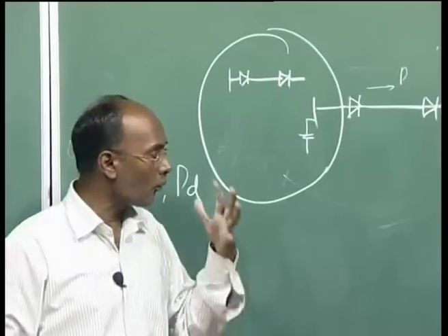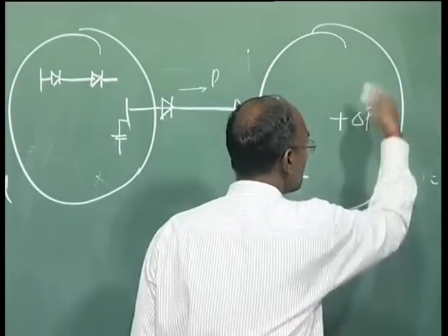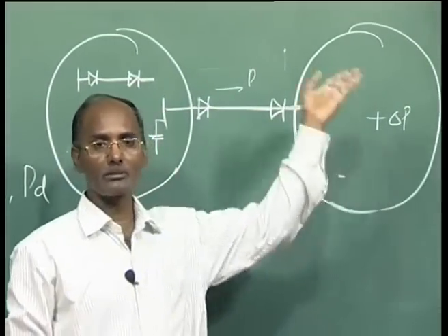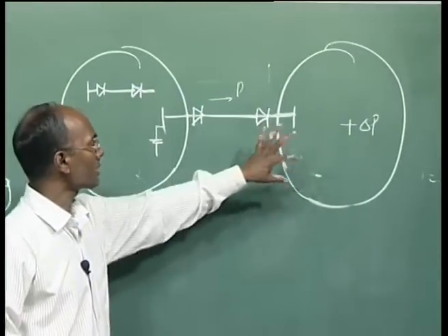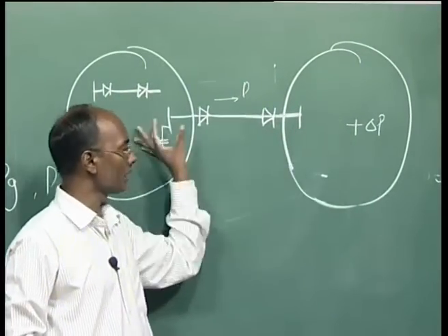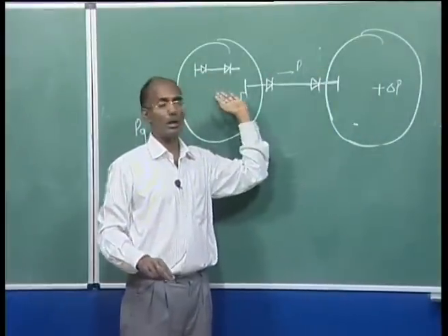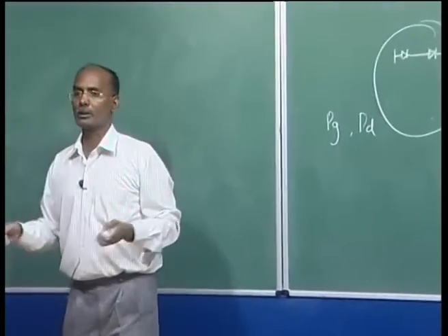If this P is higher in this zone and it is also injecting, the frequency of this system will go up. So it normally depends on the agreement between this area and this area; if there is more power here, it can come to this side or that side. So we can control the tie line power between the two areas very effectively.